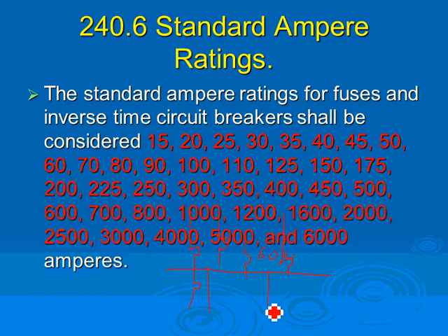So the idea is this is a 6,000 amp switchgear, 6,000 amp circuit breaker, and we're pulling all the loads from it on the switchgear. That's the only way. Do you guys have generators, all of them? Yeah. Okay. Big generators, but Excel will never give you more than 3,000. 4,000 you have to push a little bit, but I don't know about other utilities. Did you guys install a 4,000 amp service? 4,000, but they wouldn't give you more than 4,000. They like to even limit you to 3,000. If you want more than 3,000, they give you two 3,000s or three 3,000s.